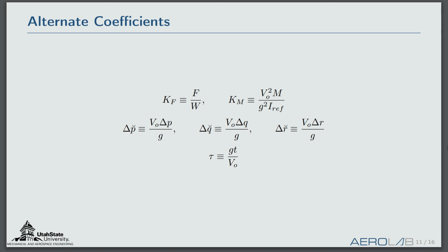We actually get a single non-dimensional time variable, even though our system is uncoupled between longitudinal and lateral. And that's amazing. So just to give you an idea, whereas in the traditional sense, when we had non-dimensional eigenvalues of our system, we wouldn't be able to compare them because they wouldn't have the same non-dimensional unit. They wouldn't have the same dimensionless time variable. But in our system, we have a new dimensionless time variable that is the same across linearized longitudinal and lateral systems. And that means that we can compare these eigenvalues before we even redimensionalize them.